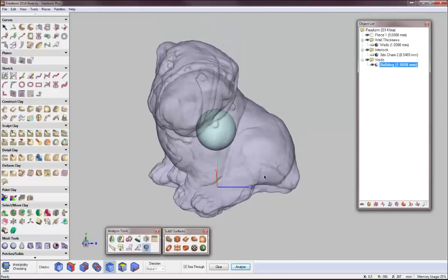So you can see those are 3 tools that I happen to use all the time. But there are some others I'll just highlight. One is overhang. So if I have a part in a certain orientation, I can control the direction here. I can check to make sure that that part with that amount of overhang will print properly. And I can even change the direction and flip-flop it around to print it in a better direction so I have less overhang.